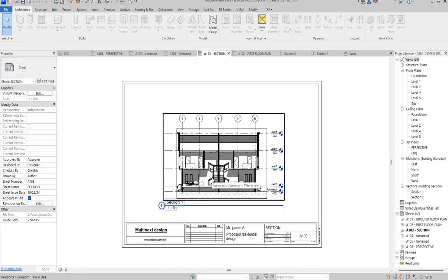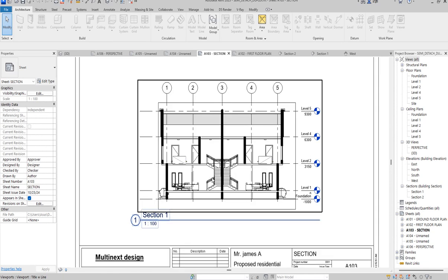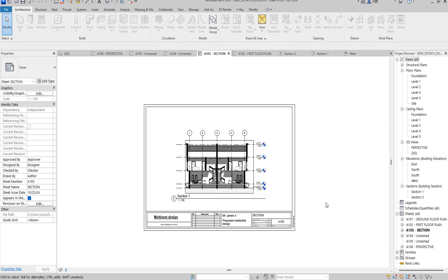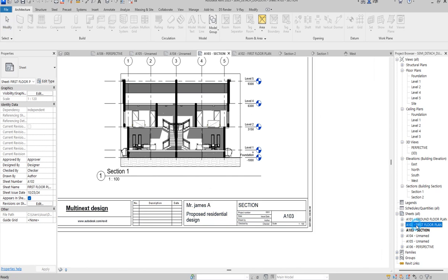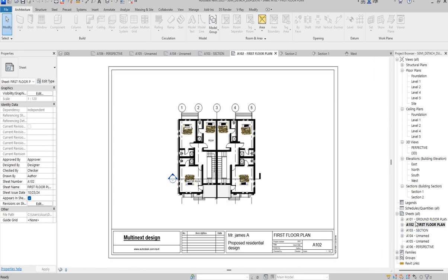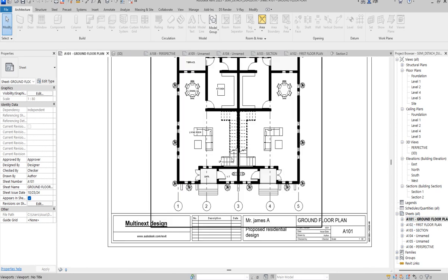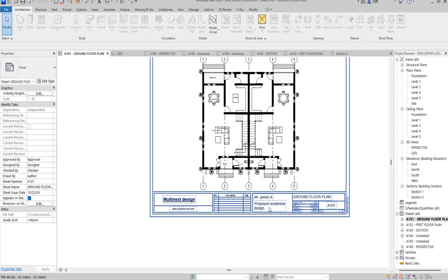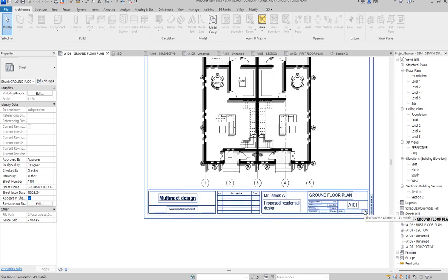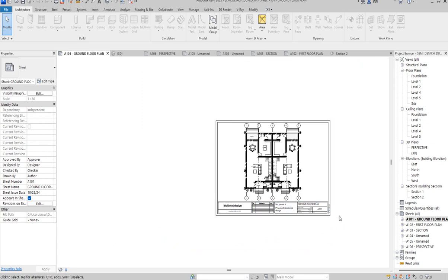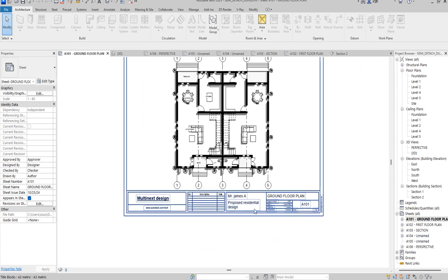In the continuation of the Semi-Detached Duplex we are working on, in the last episode we were able to bring the sheets into the paper space, so that when we arrange all this, we touched on how to bring the drawing to the sheet and how to edit some of the title block for your work, if you have a field that you want to change.